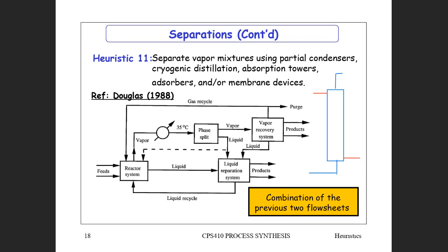Now let's think of that DW simulation where we had methanol and synthesis gas. What we did with that methanol, we put it into a vapor liquid separator, which is essentially this thing, at 40 degrees C, and we got the methanol coming off here fairly pure, so we didn't even have to separate. The vapor had some methanol in it, but it also had a lot of synthesis gas. So we can put that synthesis gas through a packed column.